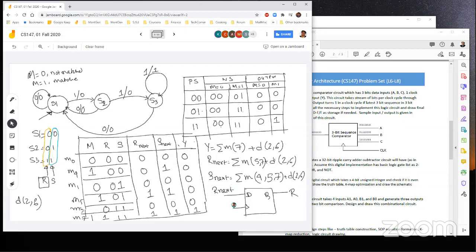With the clock and etc. The clock doesn't have the symbol, reset, etc. is there, but mainly, for each state variable, you will have one D flip-flop whose next state logic is coming into the D, and Q is the present state logic. So that way you define the construct of the circuit.